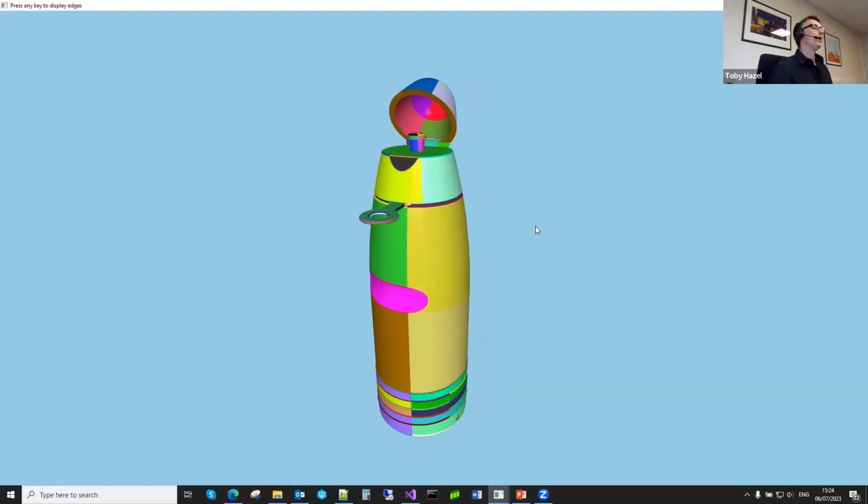And we've done this by using the PT app surface data, which Rich mentioned earlier. This is an addition to Polygonica in 3.2. These are set on loading through the bridge to indicate the CAD surface patches, and they're set on each of the Polygonica faces. When I say a Polygonica face, I mean an individual polygon within the mesh.